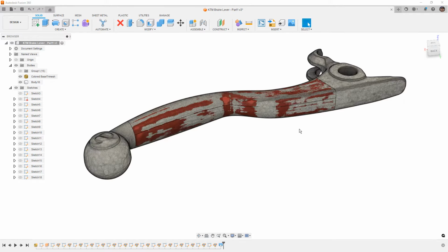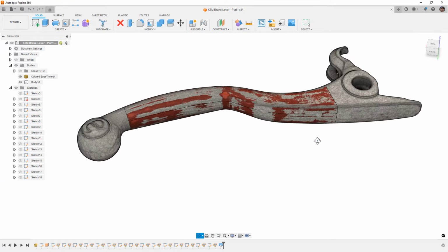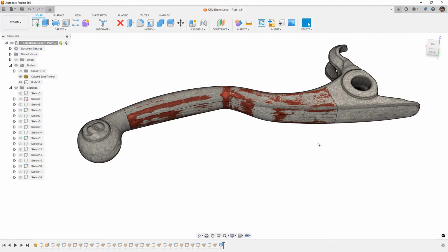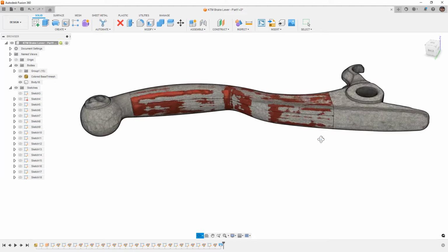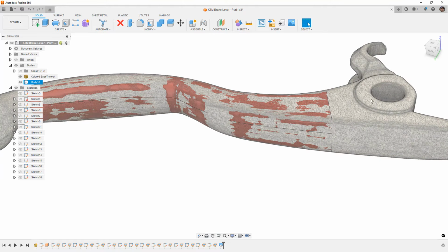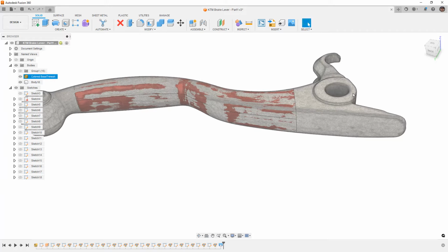All right, so now that we have this lofted piece here, as I mentioned, I'm going to do this over a couple different videos, but now that we have this lofted piece, it looks pretty good. I mean, on the surface, everything looks to be pretty nice. But the problem that we have here is trying to connect or carry it out to all of these other prismatic features. So again, right now, if this thing had to be machined, then it would be more difficult than if we had designed it in sort of a prismatic nature. Because of that, carrying on and building these other features over here becomes tricky.